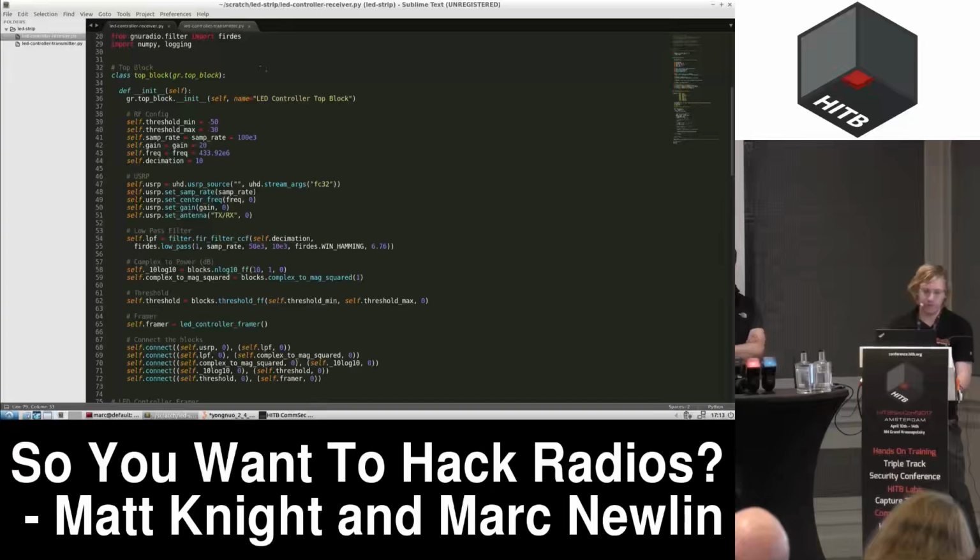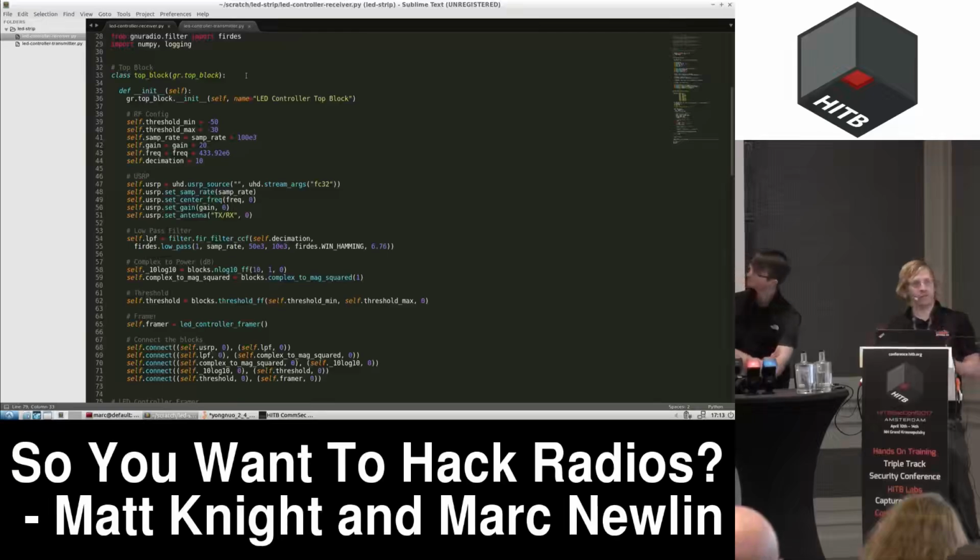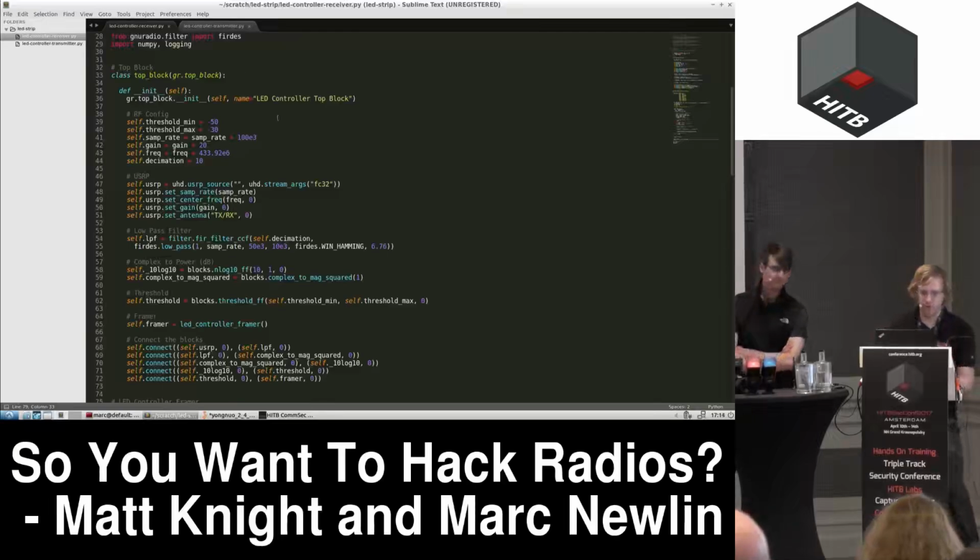And when you're doing this GNU Radio stuff, a lot of people like to use the GNU Radio Companion software, which is perfectly fine. But when you compile a GNU Radio Companion flow graph, it just produces Python code. So I prefer to just write the Python code. And in this nice low complexity case, it's not too much code.